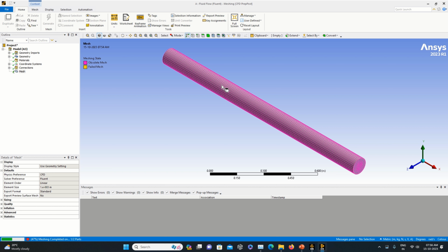You can click on this button and change the mesh size as per the requirement. In the earlier case, 0.01 generated quite easily; now it is taking time, that is 0.001. If it is not working in your case, you can click on the red symbol over here, and this will stop the mesh generation. But we will wait for some time.